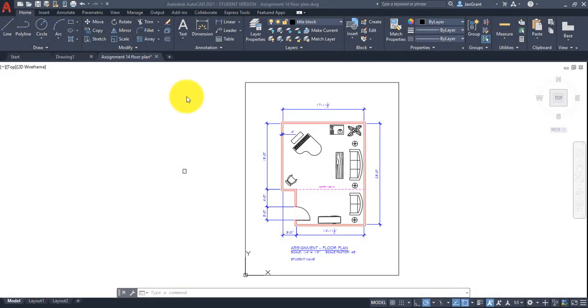In this video, we'll be taking a look at three basic things. One will be to understand scale factors when objects are bigger than a 1-to-1 scale. Another is to look at blocks like these pieces of furniture that are in this drawing. And then the initial setup of taking all of these settings and creating a template file.